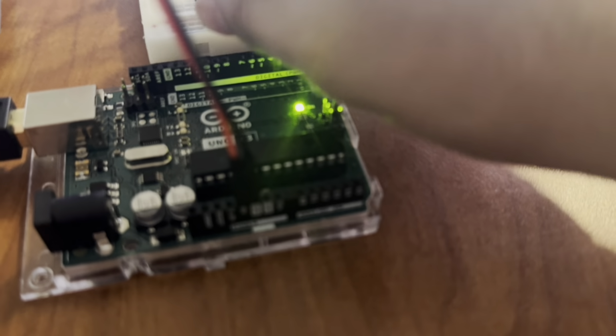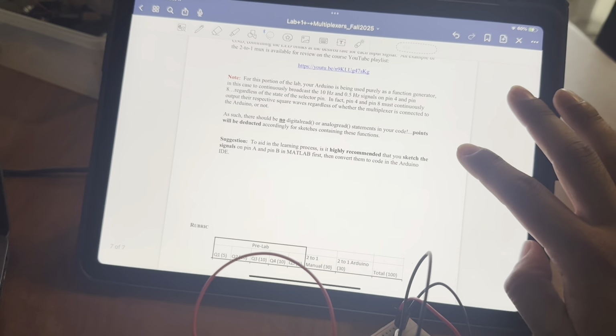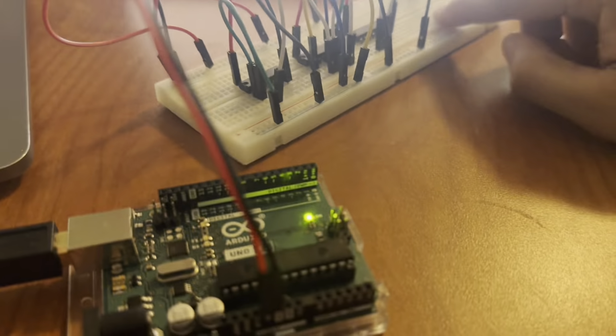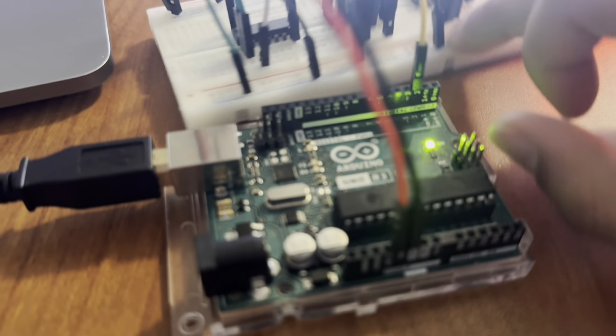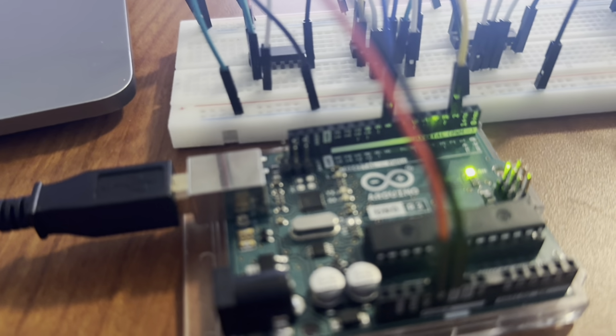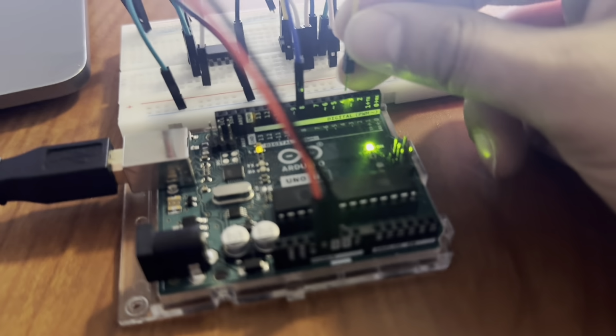Now, switching gears here, we can run a test where we can demonstrate our LEDs blinking, whether 10 Hertz or 0.5 Hertz. So I will connect my input A to 2, and I'll put my input B to pin 8. Actually, I will move my pin A to 4.